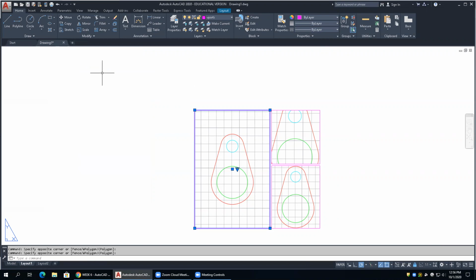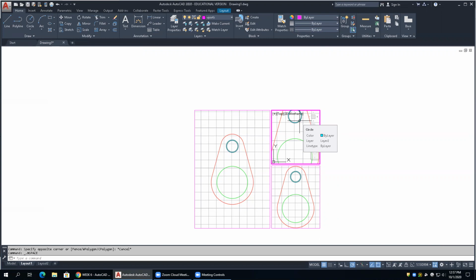So we're going to come into this other viewport right here, this top one. And what am I showing you the scale factor is for that? 2xp. So 2xp means times paper space. So this would be a 2-to-1 ratio. Okay? Now, I want to show you a cool little thing here. What we want to do is zoom this from the center of the object that we're going to zoom out. So I'm going to use that top circle, okay?